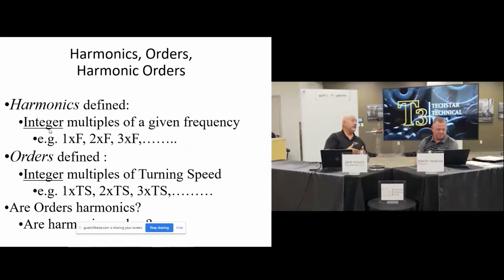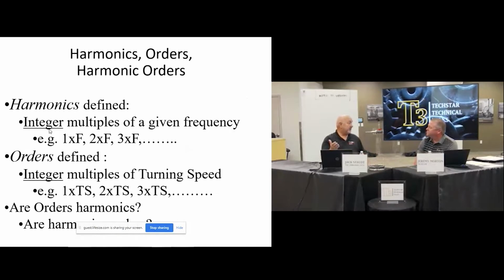Yeah. So you may see early stages of an outer race defect at maybe 8 to 10 times the outer race frequency, and maybe start seeing some sidebands with it too as it degrades. They'd be non-synchronous, but the harmonics would just be harmonics of that fixed natural frequency.